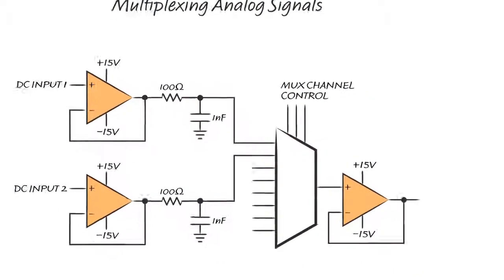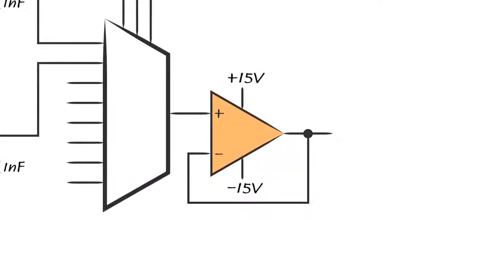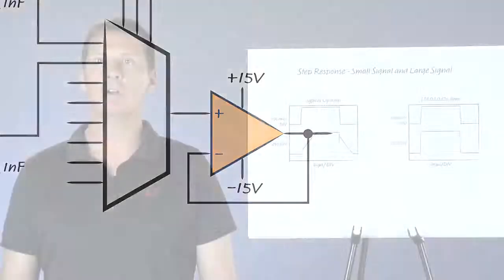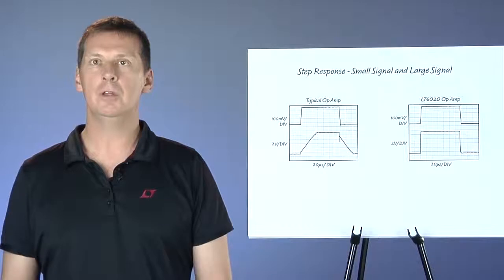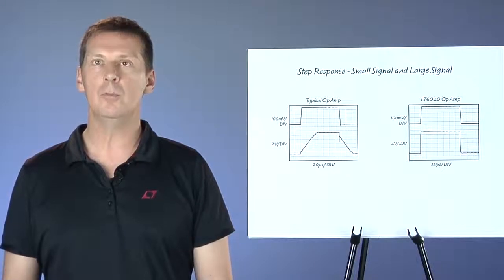Because the switches inside the mux have non-zero on resistance, it is often necessary to buffer the output using an op-amp. Now let's talk about how to choose which op-amp to use in this spot. Op-amps with low power consumption tend to be slow. In particular, op-amp slew rate is often very closely related to the op-amp supply current. That is because the internal current available to charge internal capacitors is a fixed proportion of the op-amp total supply current.